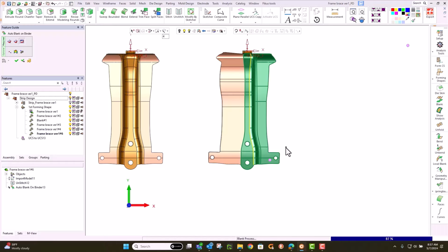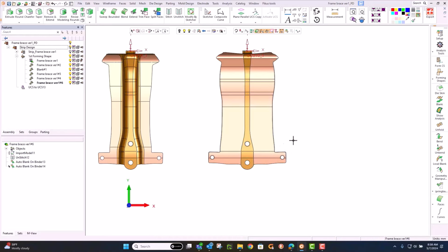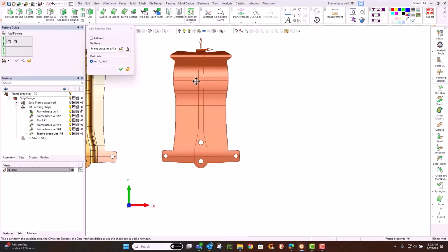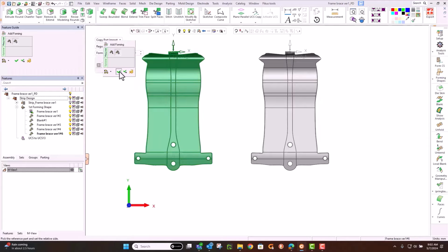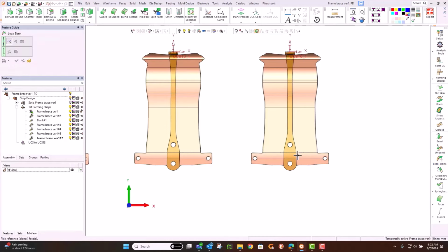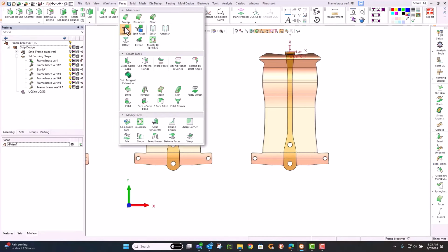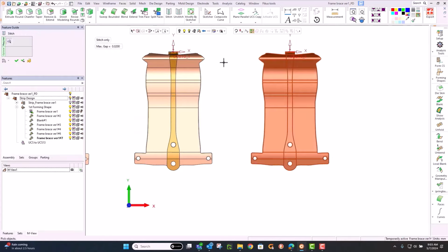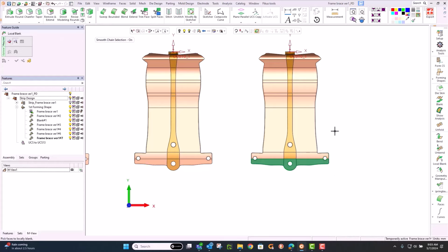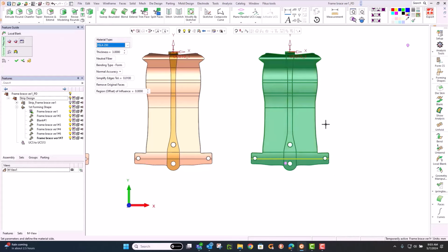So here we have what you might call your curved form. We want to lay that out flat and see exactly what it would look like as a true blank. So make sure all the pieces are together here and just do what we call in this case a local blank operation. And it will take the curvature out, laying it flat for me, so I can compare it to the initial blank, or I can go ahead and start working with it as is.